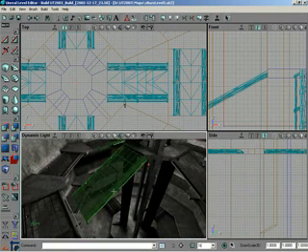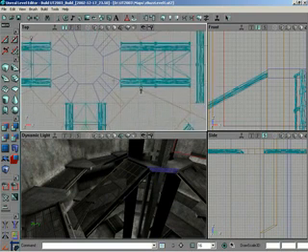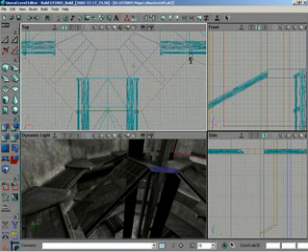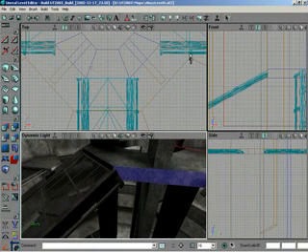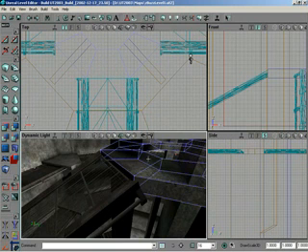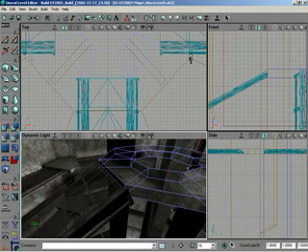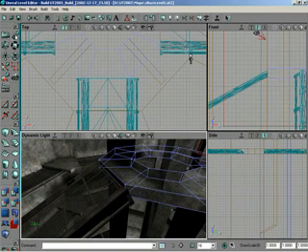Very nice. Now, do we want to go ahead and do our editing on that ring right there where the player is going to get off from the elevator first? That sounds good. Okay. You can see where these vertices are, it doesn't quite match up with the edges, and it doesn't look that great without them matching up. So what I'm going to do is grab this ring that makes up the little walkway here. Let me grab this little green scroll bar, scroll back up to the top so I can get to vertex editing.